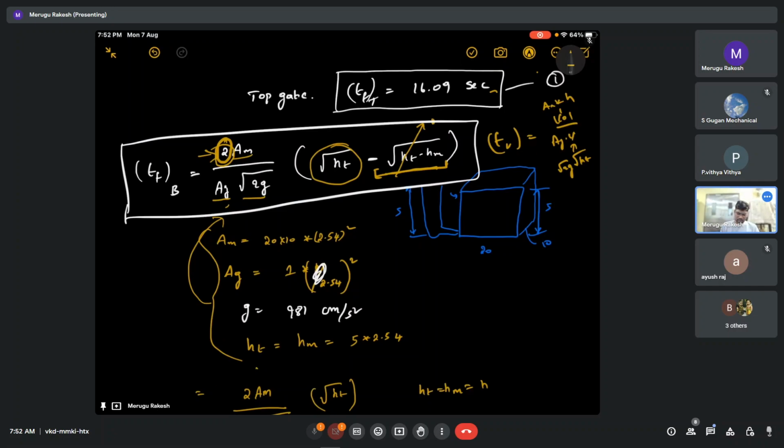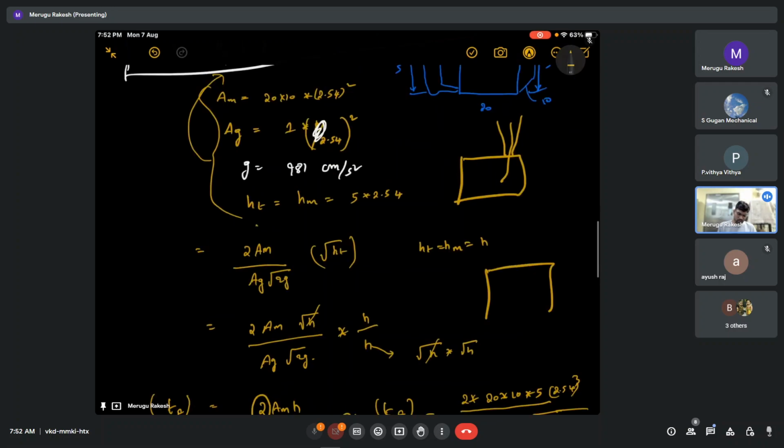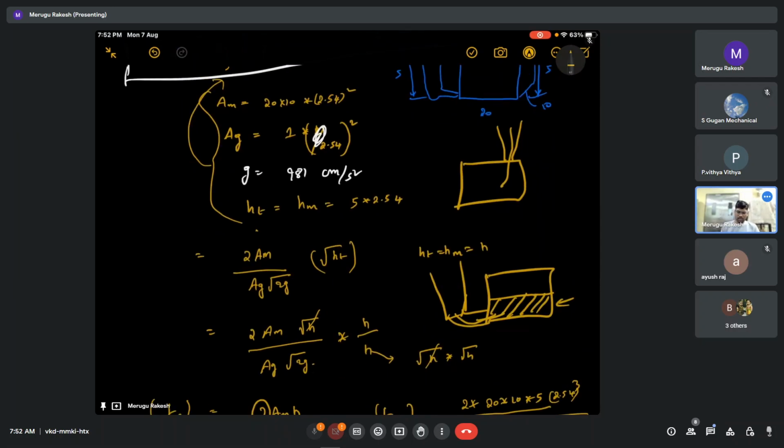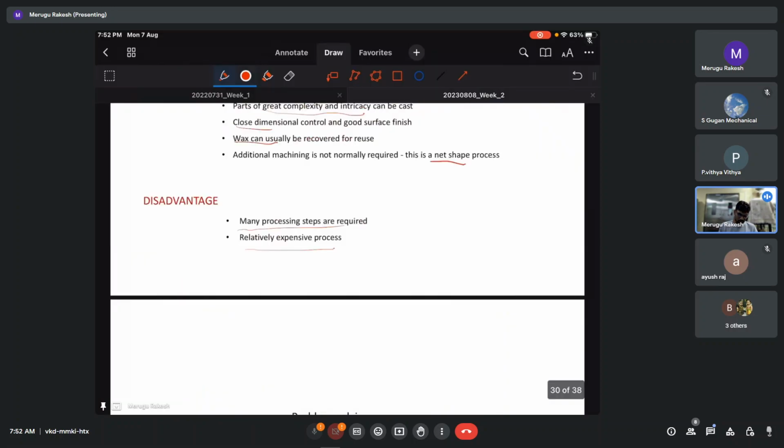And the final way is that it is pretty clear, right? If it is a top gating system, we have very high velocities to fill the mold cavity. Whereas in the bottom gating system, we're always filling from the bottom, so we have to overcome this weight in order to push the metal inside. So this is always going to be lower velocities compared to the top. And the mixed gating system will be in between. That is the answer for this. The answer will be 0.5 in this case.